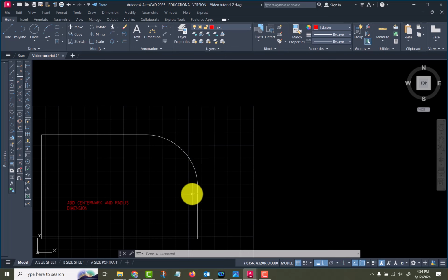that is rounded off. Usually that doesn't get a center line. I mean, sometimes it may, it depends on the sketch or whatever. But usually fillets don't get center marks or center lines. It just all depends on the object and the shape of the object. But in our case, yeah, we're going to put them in.